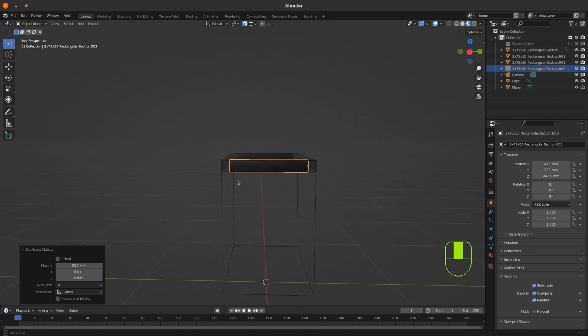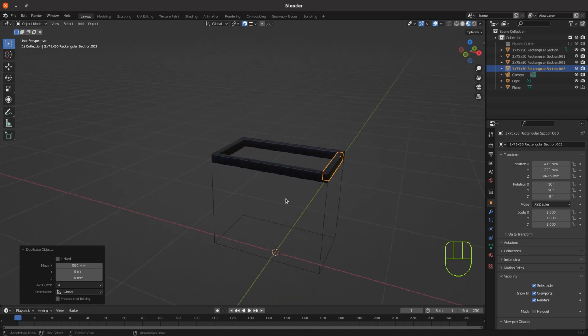Because of the material constraints I said in the first part of this project, I'm working with 500mm side pieces. If you wanted to miter the corners, you could make the frame slightly shorter on the x-axis to have the extra steel to be able to cut the miters on the corners, or just buy a little bit more steel. And I'll cover miters in the next video when we look at the angle iron frame that makes up the uprights and base of the table.